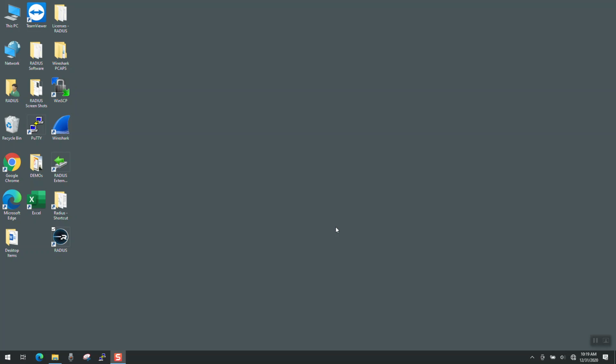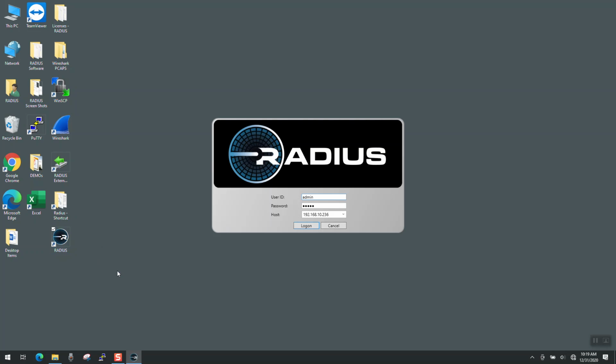In this video, I'll demonstrate the basic functionality of the Radius graphical user interface. To get started, double-click on the Radius icon found on the desktop. The logon box will be shown. By default, the user ID and password are admin and admin. The host IP will be your gateway IP address.